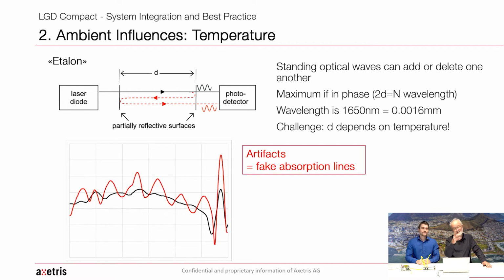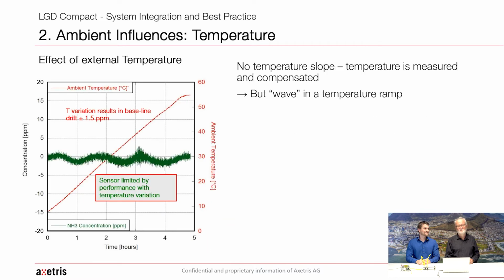But then when you add some reflection to it, you will get these waves shown in red here. And in this specific case here, it would add to the signal, and you would think you have a much higher concentration of gas than you really have. But depending on distances, temperature, and so on, this could also go in the other direction. And both facts are not so great.